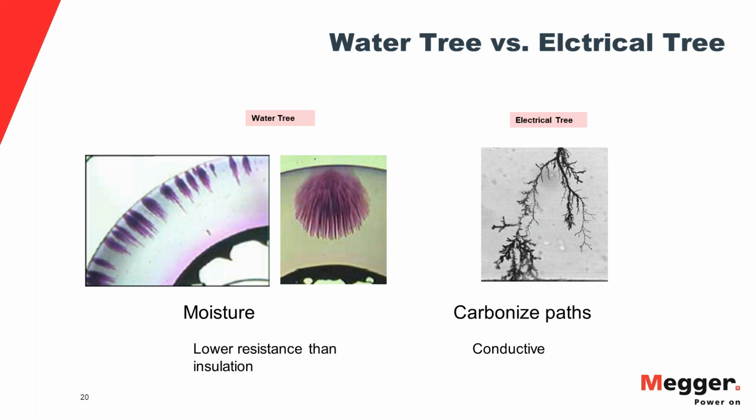And then you come back to the cable and you might get a failure because over time, the insulation now has aged enough that the water tree content is so high, the length is very high, and you've got 2, 3, 4, whatever critical length water trees. And within the 60 minutes, you will flash over the most critical ones. And then you come back after 2 or 3 years and repeat. And this is kind of a little bit of the price you have to pay for the proactive maintenance. It's a hamster wheel. Once you start, you can never get out.